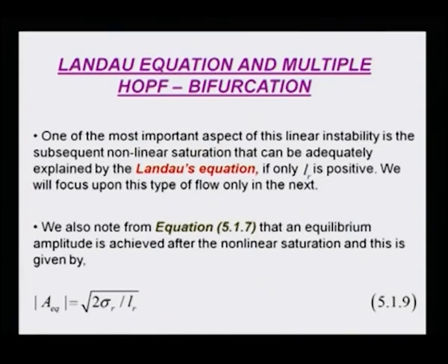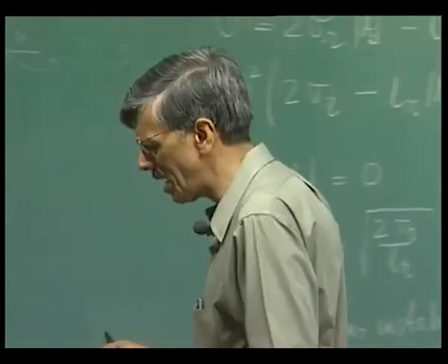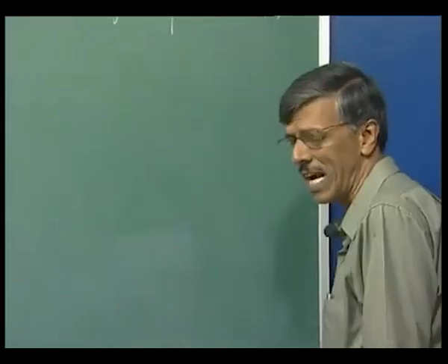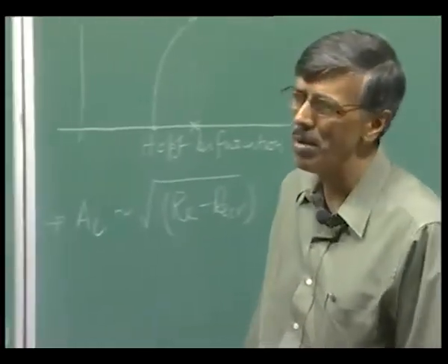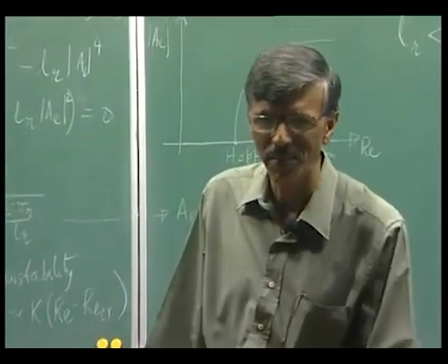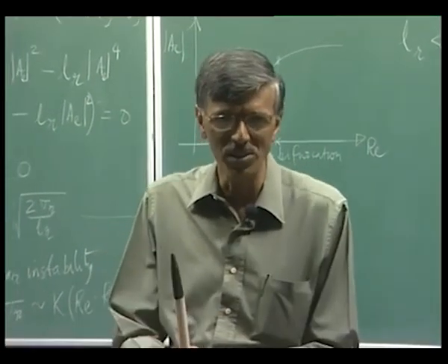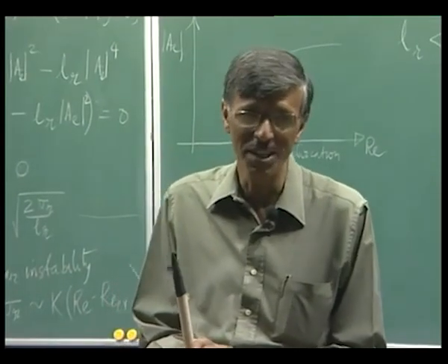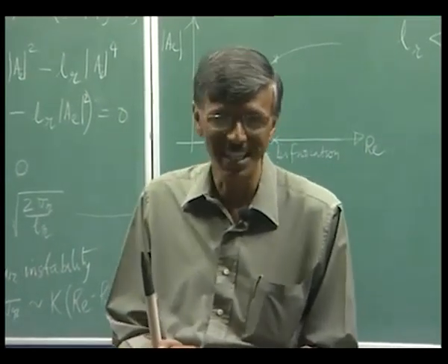We did also talk about the equilibrium amplitude as given there, we have shown it. So, we could talk about an equilibrium Strouhal number. You know, there were lots of attempts in the 70s and 80s. People have spoken about describing this nonlinear action in bluff body flow instability by measuring Strouhal number. It is an easy thing to measure, because unlike the amplitude, you will have to put in a probe, and I told you about Kovasznay's experiment in the late 40s. When he put in a hot wire probe, he saw the vortex shedding disappeared.